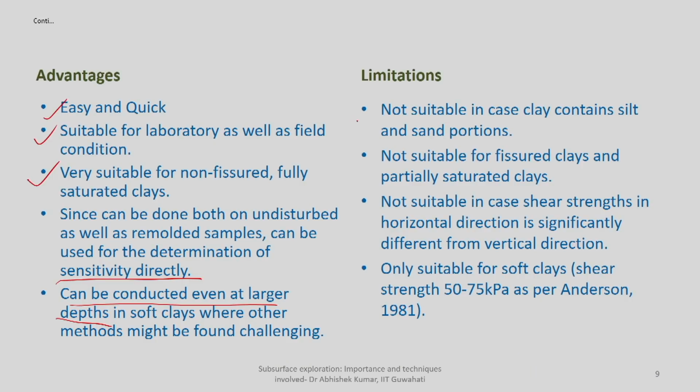So, these are the advantages we have discussed. Now, we will be discussing the limitations. This test is most suitable for purely cohesive soils. It may not give a very true indication when the soil is mixed with silt and sand portions. It is not suitable in case fissured clay is there or when the soil is partially saturated.